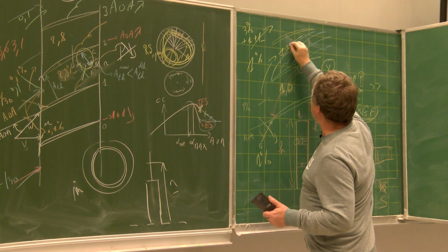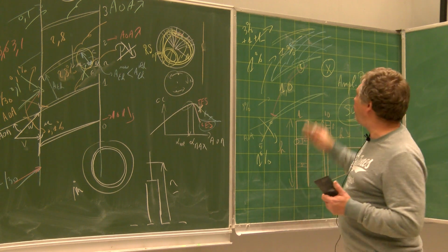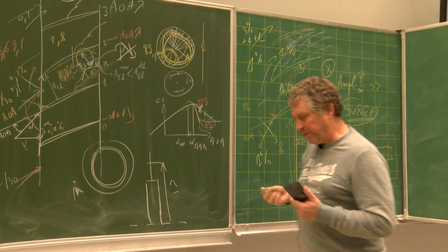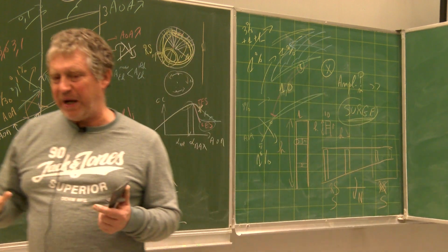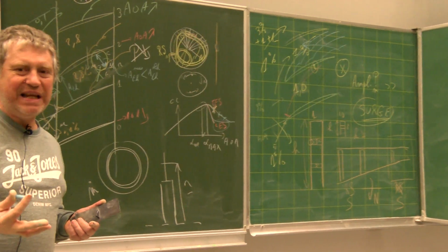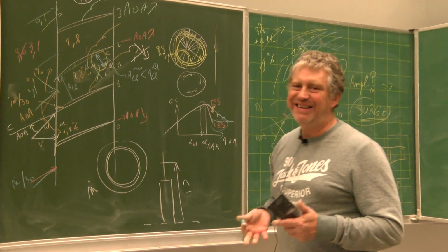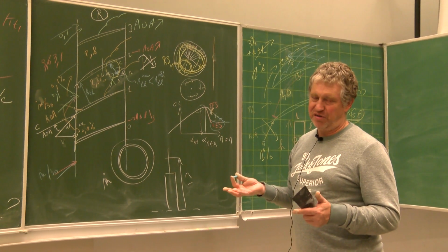So you see that a trailing edge separation, when growing, becomes a leading edge separation. And so if you have a large trailing edge separation, it also leads to surge. So you see that rotating stall can degenerate into surge.